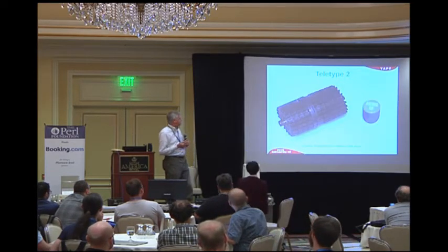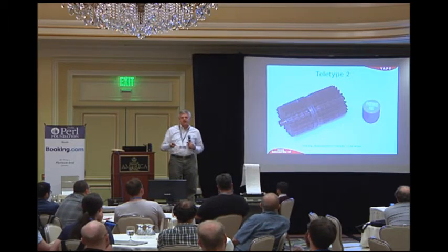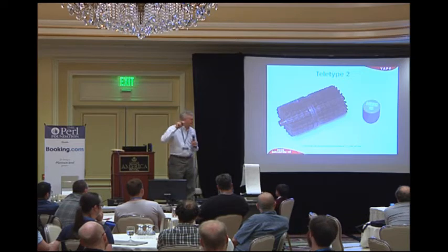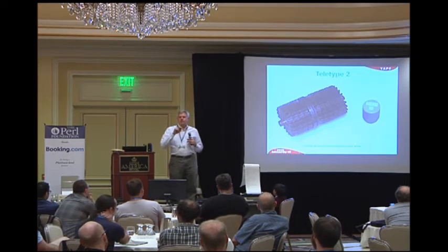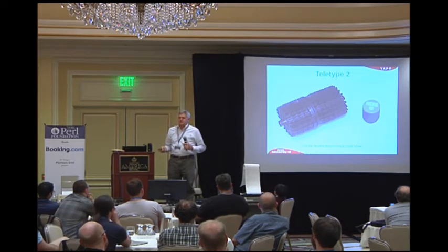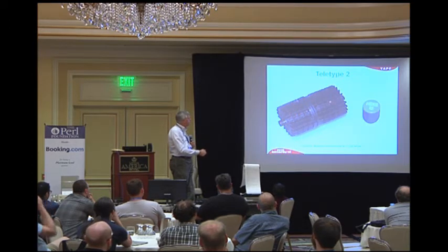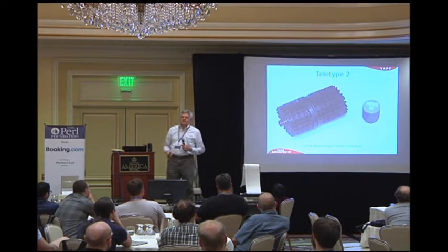But what it was called was the answer back mechanism. You could program in these devices so that when you hit the answer key, it would print out a 20-character message. So it had like a 20-character buffer. And these pins here, each one of these rows is for an ASCII bit combination. So you break off the pins to represent an ASCII value.